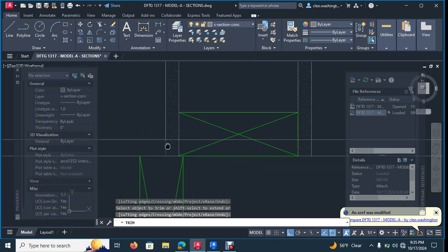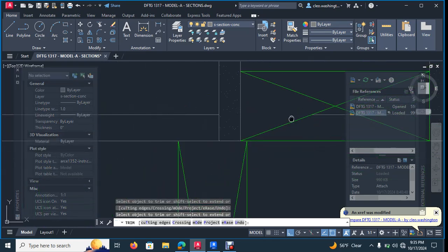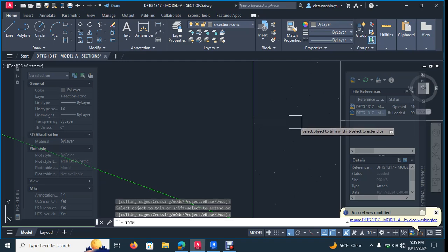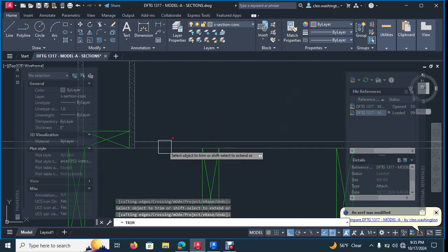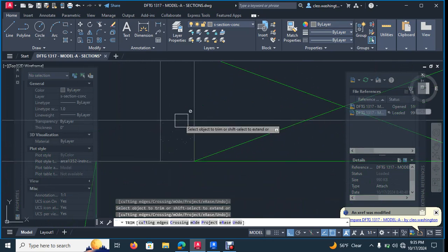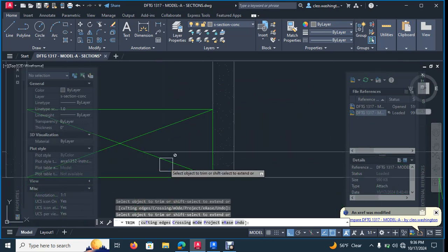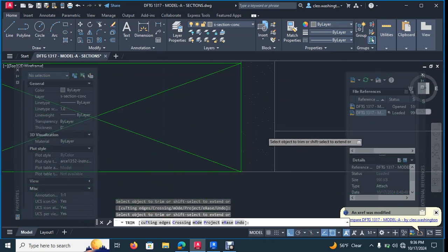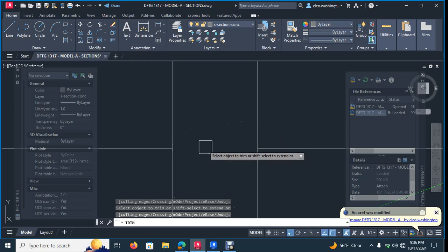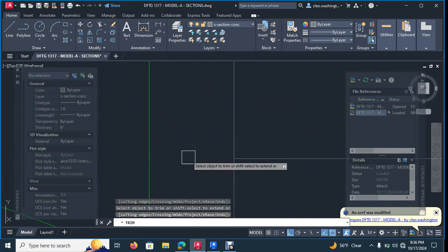You want to do the same thing at every location where there is a wall and the 3/4 inch plywood is running into the wall. You don't want it going through the wall. It's going to butt up right to the face of that wall. Okay. Now, a lot of people don't typically show this, but I'll draw my sections very detailed. That way, when you actually start doing your wall sections and your section details, a lot of the details have already been drawn. Okay. That's just how I like to do it. I think it works better that way.